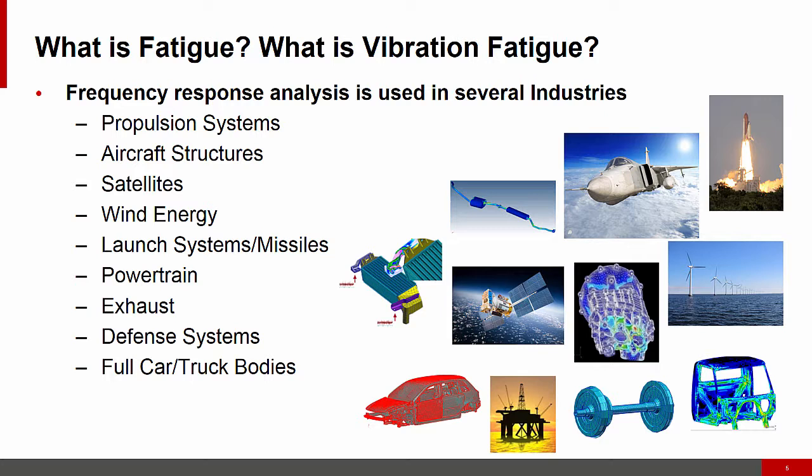Vibration fatigue is the estimation of fatigue life when the stress histories applied to the structure are random in nature. That means they're not repeated in the same manner. In this case, these types of loads can best be described using a statistical process.